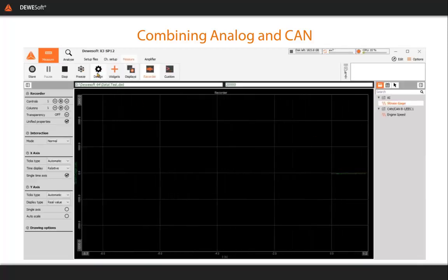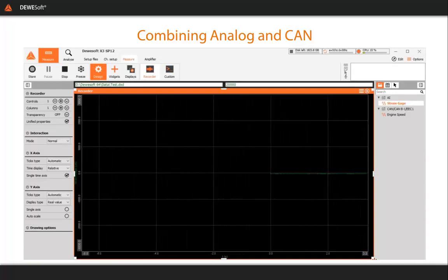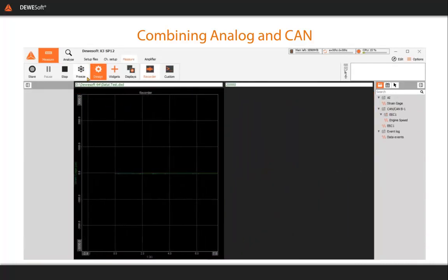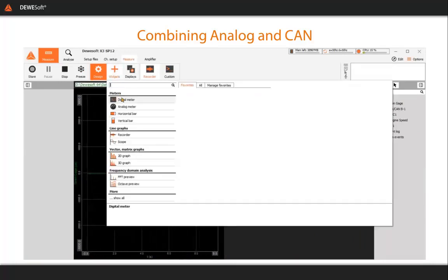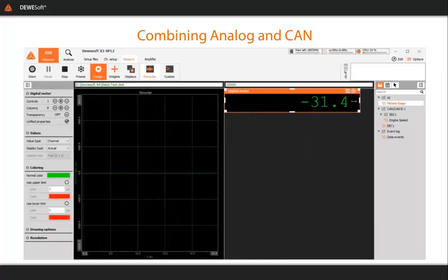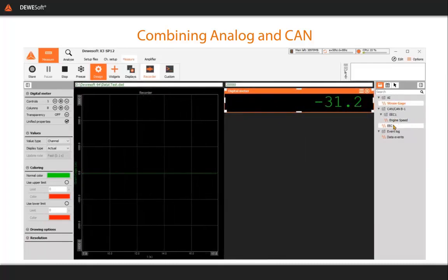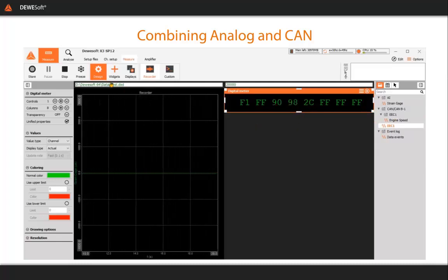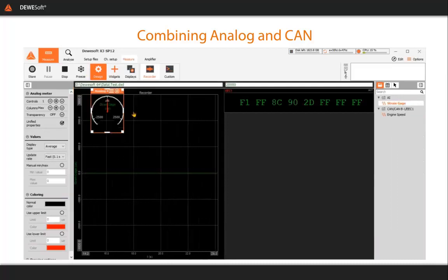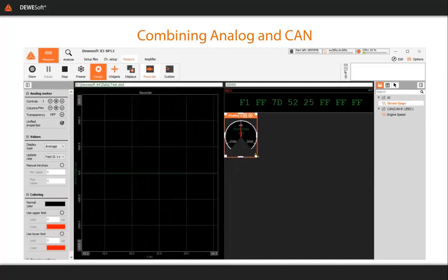So we add those values in, and we can see an equivalent down in the lower right hand corner almost immediately. Now we can start reviewing the analog and CAN data visually, and all we're going to do here is add the CAN signal in at the same time as the analog signal, so we can see them happening together. In this case, we're going to put that engine message so that we can see the entire message that we're filtering out, if you will.